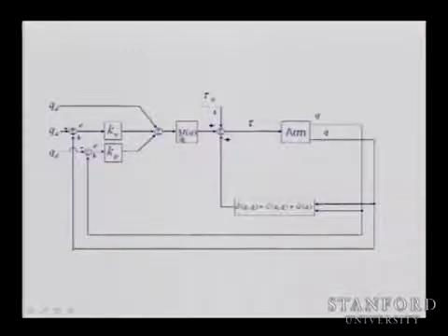So the torque is m hat times torque prime plus those estimates. And then we are able now to compensate for centrifugal, Coriolis, gravity forces and scale our gains and decouple the system. And the overall behavior of the system will be decoupled.